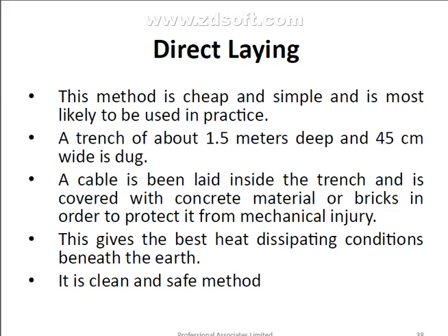So on that consideration, it is of three types. First is direct laying. In this method, it is quite cheap compared to the others, and most commonly it is utilized. A trench of about 1.5 meter deep and 45 centimeter wide is dug. A cable is laid inside the trench and is covered with a concrete material or bricks in order to protect it from mechanical damage, and this gives the best heat dissipating condition beneath the earth. So it is a clean and safe method.